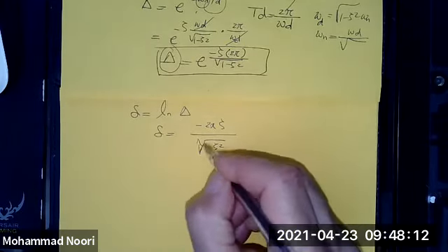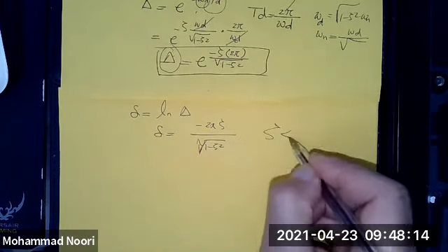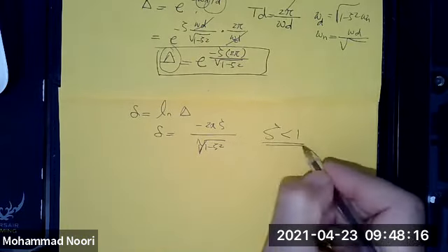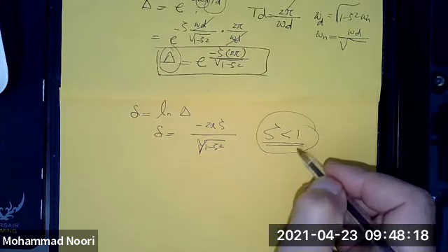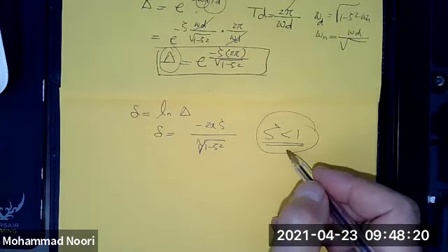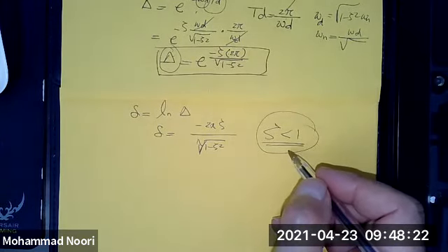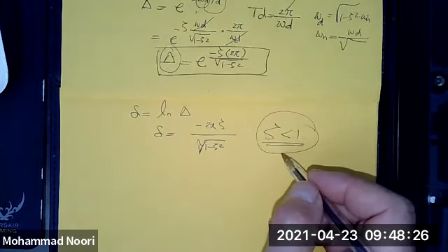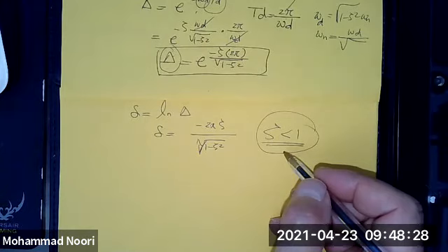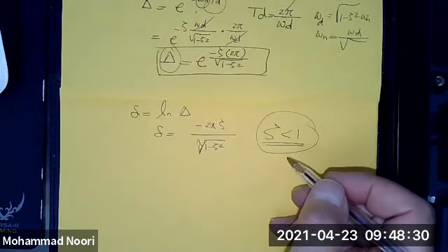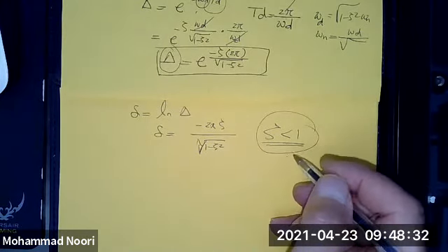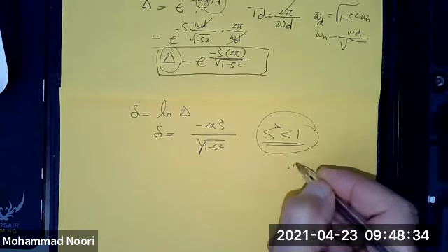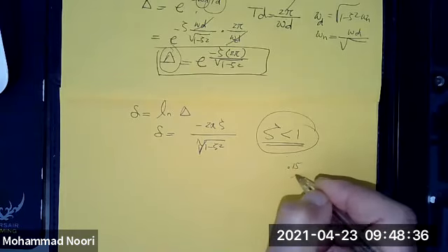Now, if you look closely, when we say underdamped systems, as I said before, the damping ratio in a mechanical or structural system is a very small value, maybe 10, 12, at most maybe 15%. Or it's like 0.15, right? Or 0.2.